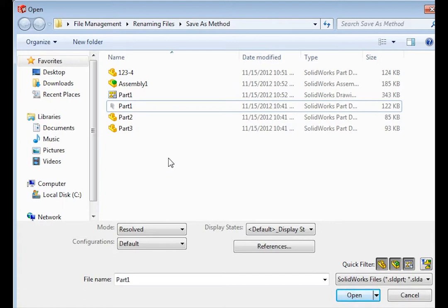The Save As procedure I just went through is effective when renaming a part that's not used in many places. A typical case would be during conceptual design, when you haven't yet assigned official part numbers to your models. It's okay to start a design with generic names such as base and cover. Then later, when you're committed to the design, you can actually introduce part numbers using this procedure.